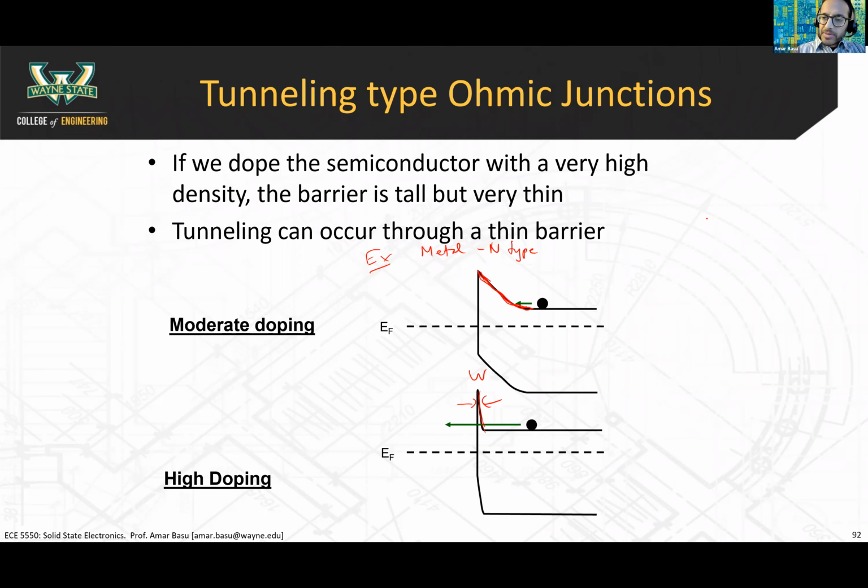So let's say I have an N-type semiconductor like this, and I want to make a metal contact to it. So I can put a metal contact pad on top of it, and this can be connected to my electrical circuit. Okay, so I have one contact into the semiconductor like this. If I make this contact with a metal, great. I have a metal semiconductor junction. Now, in this case, obviously, whether this junction is a Schottky barrier or an ohmic junction depends on the work function of the metal and the work function of the semiconductor.